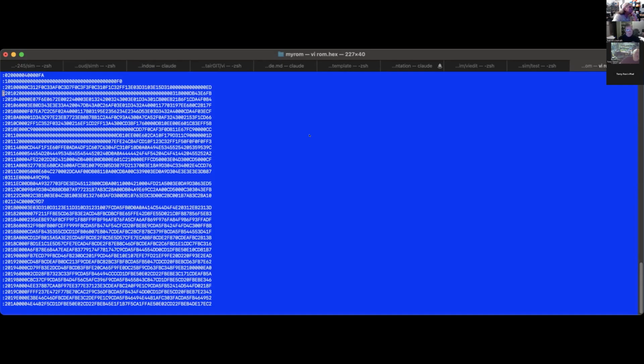You'll notice that the first ends in a 0, but that just means it's 8 or less. And then the next one is a 16 character, 16 bytes. And the third row down is the 32 byte with a checksum of ED. And the first characters in the file are C3. Yeah, just like you said. And that goes in the 866 and it programs great. I haven't done it in a while, but I didn't have any problems with it.